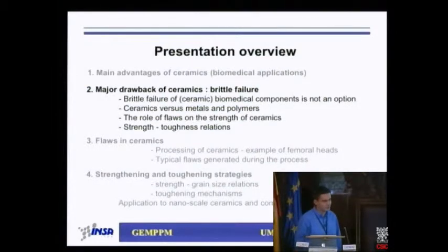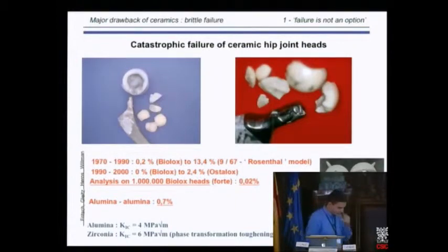So ceramics are interesting, but we have to face brittle failure. Of course, for biomedical implants, I would say failure is not an option. When you see something like that, you are not happy with this kind of failure. This is failure of an alumina hip femoral head component, and this is failure of a zirconia femoral head inside the body. So of course, these are critical events, but they do not happen a lot in ceramics today.